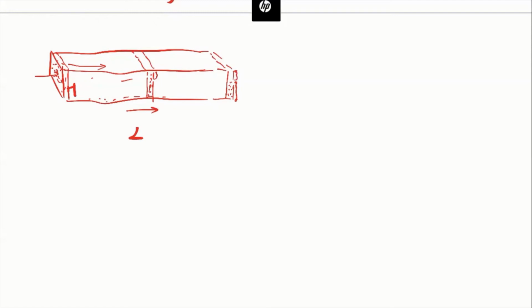So basically, we can still calculate its removal efficiency with the previous method. The way we do that is still eta equal to Vt divided by H, right? Settling down with vertical velocity. Now we just need to calculate what the time is, right?